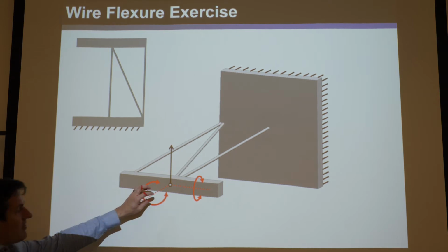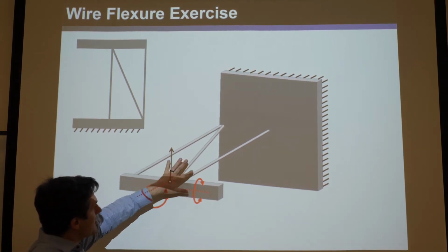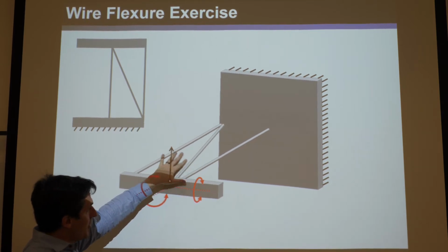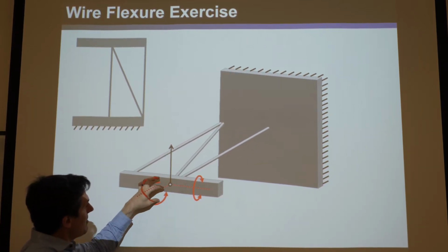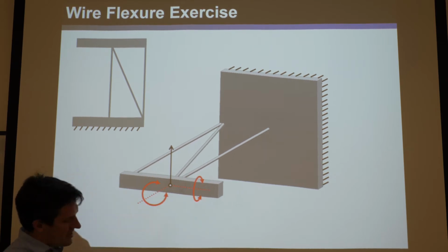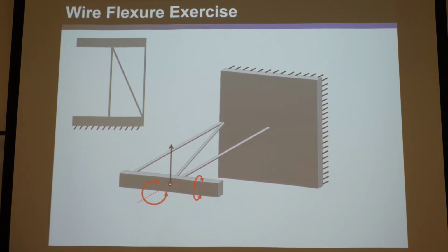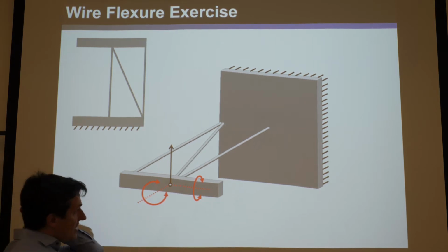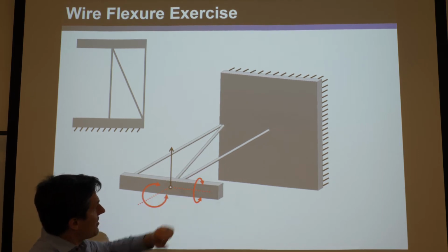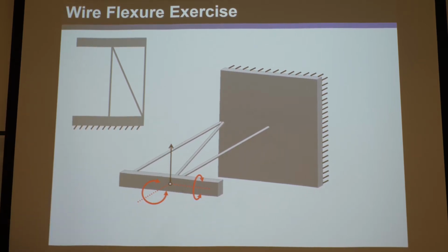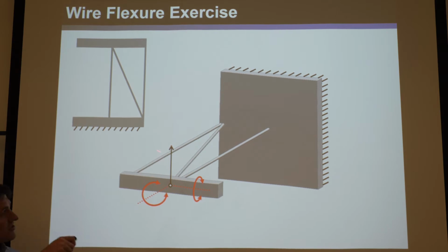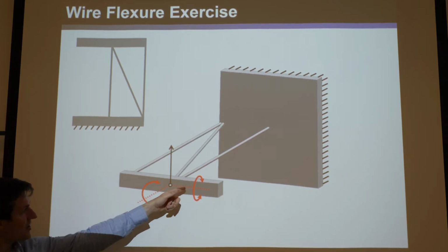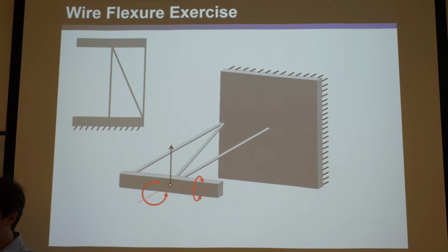So the answer is, even these ones, the translation coming out, it's still orthogonal to all three of these, still perpendicular, so it wouldn't stretch any of them. And by twisting these, or bending and twisting that, it doesn't stretch any of them. So those are obviously degrees of freedom that are maintained. And this one, the translation, is obviously the one that one kills. And those three guys are still doing their unique job, right? We got 3 constraints killing 3 degrees of freedom, 2 translations and 1 rotation. So this is indeed exactly constrained. All right, so very good, and there's those things.